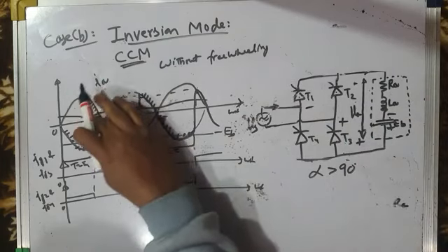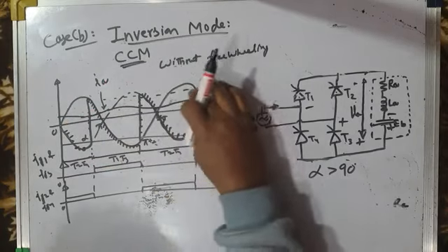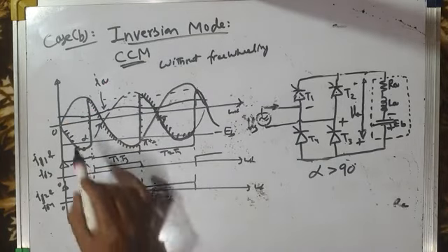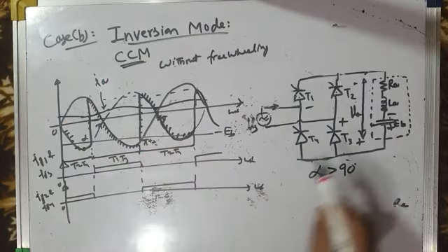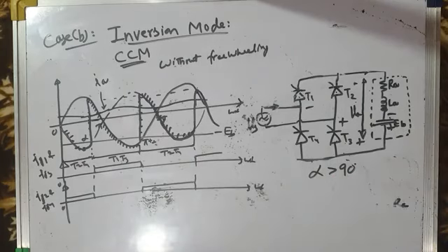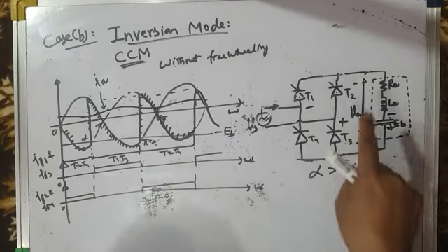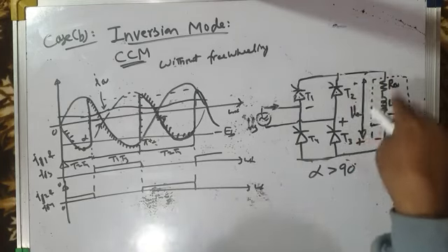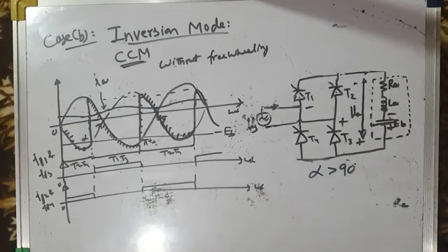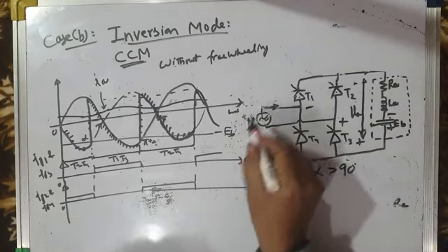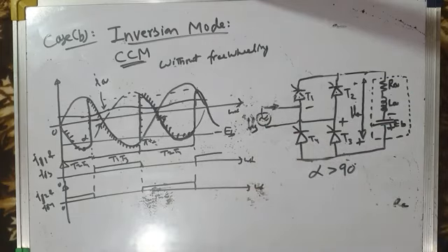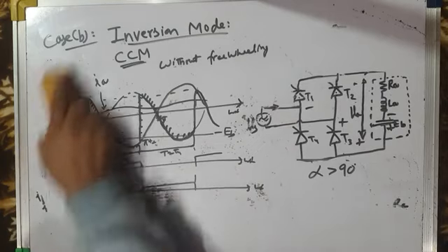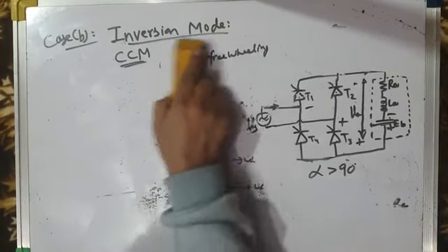If we can omit or cancel these small positive voltage segments and cause freewheeling action, then there will be no flow of reactive power between source and load. There will be freewheeling action, and whatever energy was stored in the inductance will be converted into useful mechanical energy, and that will improve the source side power factor, and average load voltage will also increase. It will become more negative for a given delay angle or firing angle. How can we do that? How can we go for freewheeling?